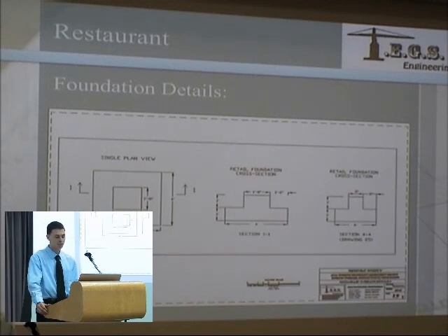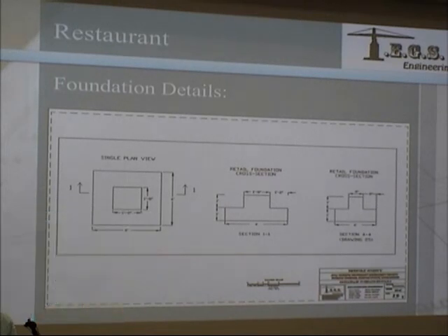Overturning, sliding, and bearing capacities of these footings were designed with a factor of safety greater than 2, and the ultimate settlement in this restaurant will not exceed 1 inch. Now I'll turn it over to Brandon, who's going to talk about the retail and residential buildings.